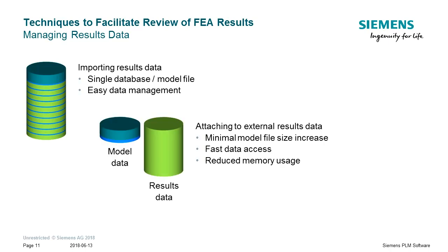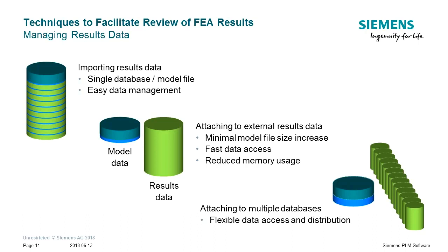Another method of accessing results by attaching results databases is also available. This allows the database files, model and results to remain intact, as the data is not required to be imported, though the address data for the results is still added to the model database. Data access through attached databases is much faster, and greater flexibility is possible by attaching multiple results files simultaneously. In a case where you can attach to a large number of results files, it's clear how this can help keep the demands on storing the FEMAP model to a minimum, speeding up file open commands and keeping FEMAP's memory footprint lower when running.